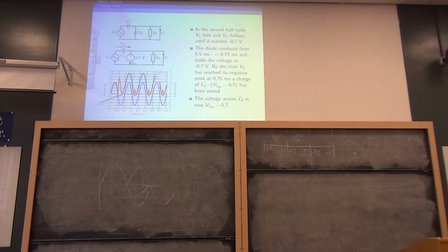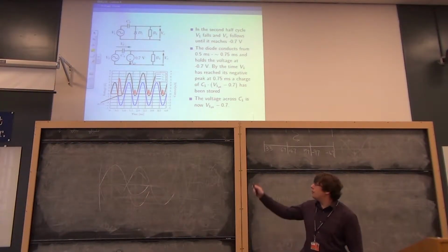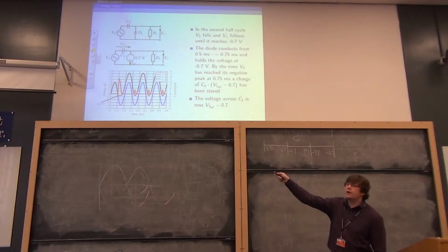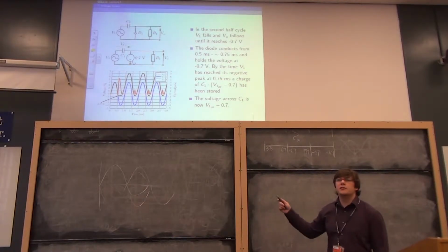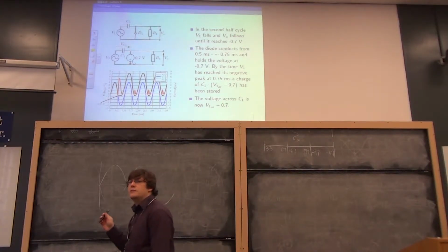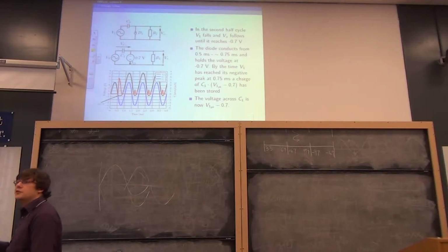So the key difference is the diode will conduct a large current, or it will conduct enough charge to charge the capacitor quickly. The resistor will not. The resistor is only really there to show you what happens on all the further half cycles, because all these little current spikes are the diode conducting very briefly to replenish the capacitor, in just the same way that in the peak detector the diode has to conduct very briefly to replenish the capacitor because it's discharged by the resistor. Same situation here, the capacitor is discharged a little bit by the resistor in each half cycle, and the diode has to conduct very briefly just to top it up.